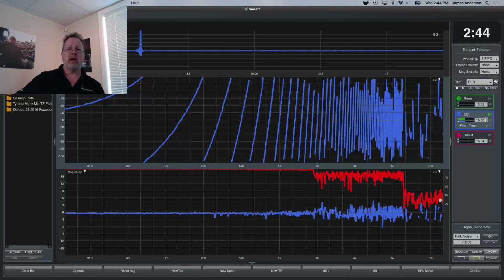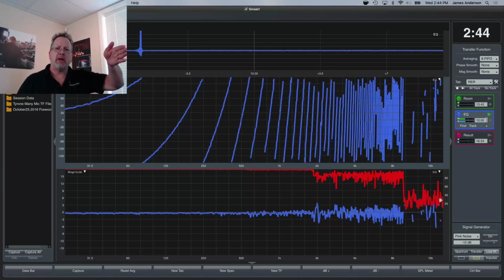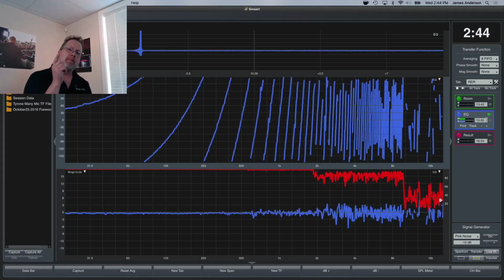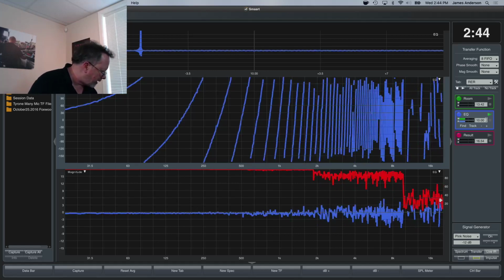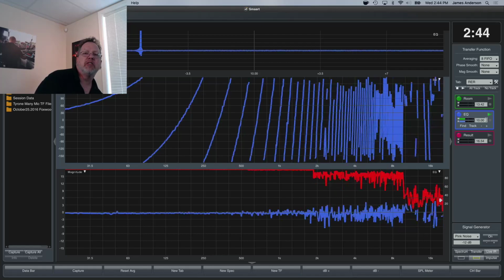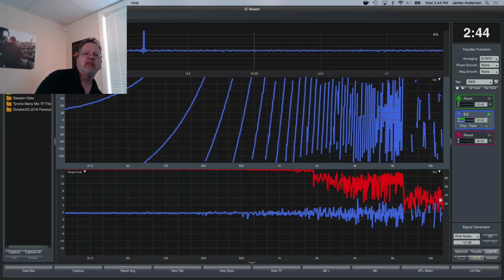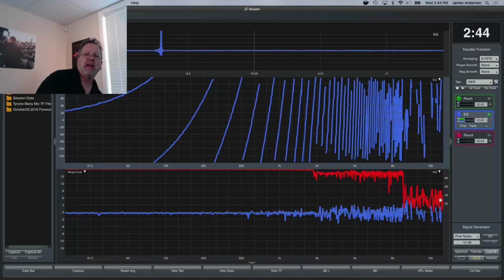So effectively what I've done is put my reference signal out. My reference signal is now stuck out here at 10 milliseconds. My measurement signal now is leading by some amount. But what I'm going to do here is change the delay through the system. And so what I want to do is adjust the system till the output of the system is arriving at 10 milliseconds.